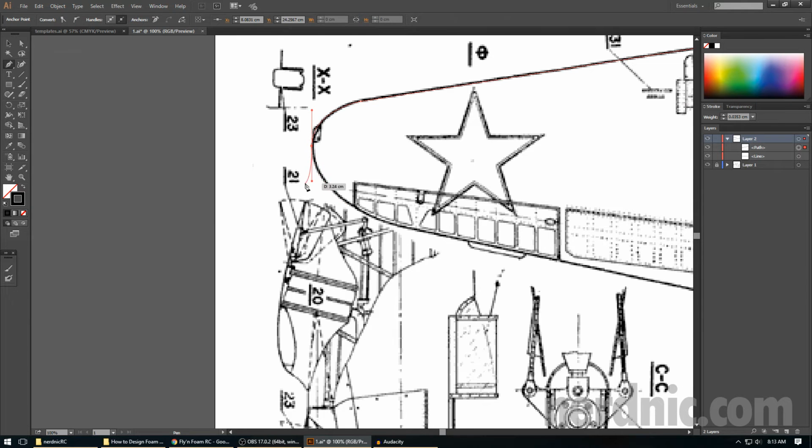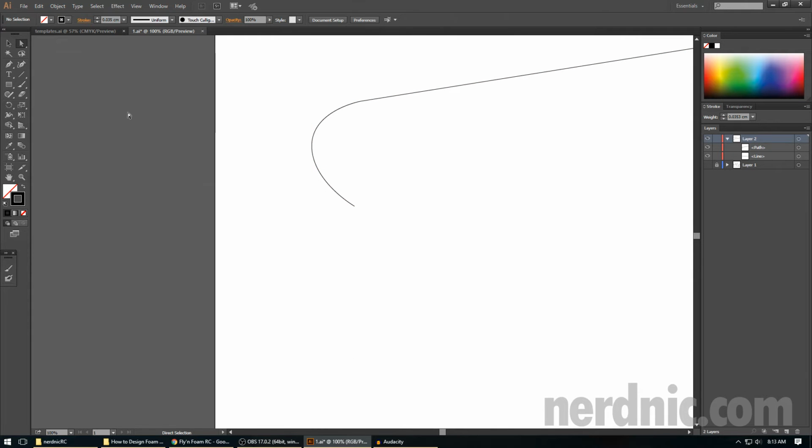Now, one thing too with this pen tool, the second line that you do, it tries to auto curve it. Now sometimes this works, right? Where if I trace my mouse around the reference, I can see, look, that almost lines up perfectly, right? So I can then just click again, and it finishes my line. Now the one really cool thing about doing the second curve, so once you do your first line, if you let it keep curving, is this joint right here, that second anchor point that was created, will always be smooth. No matter what your next angle is, so if I did some crazy angle over here, over here, over here, this joint right here is always going to be smooth.